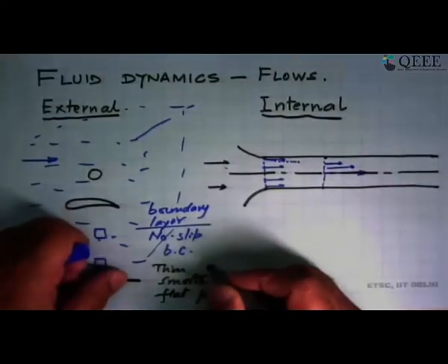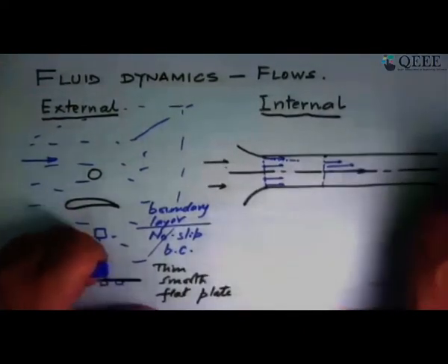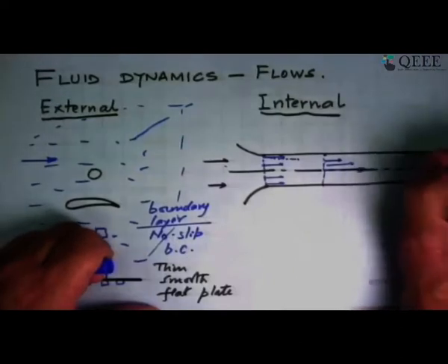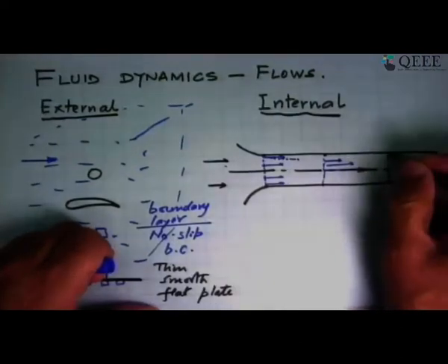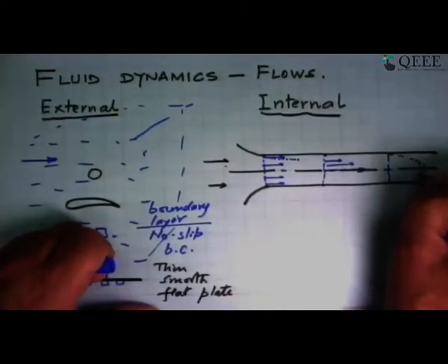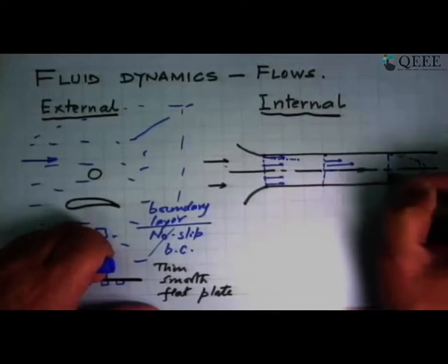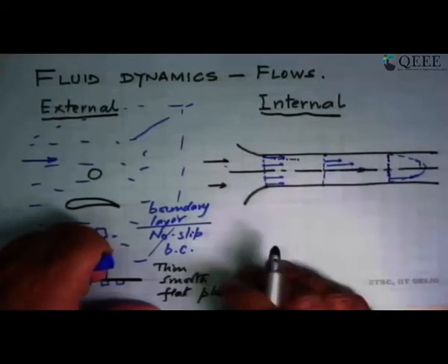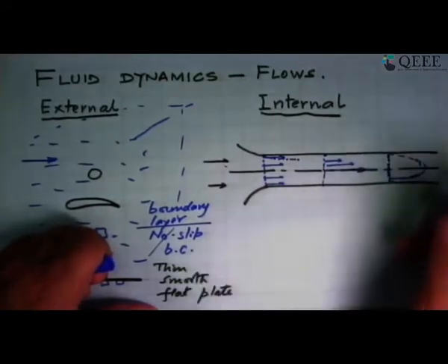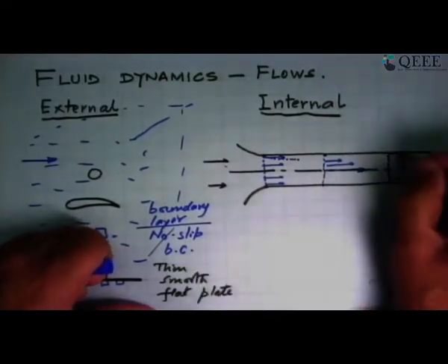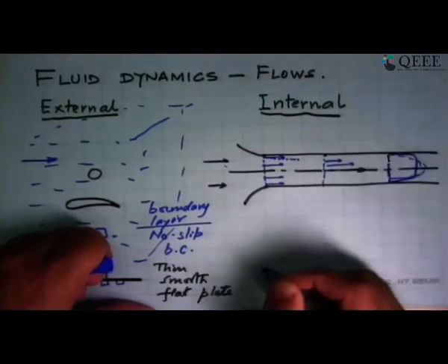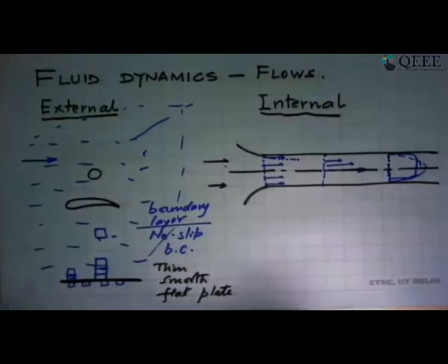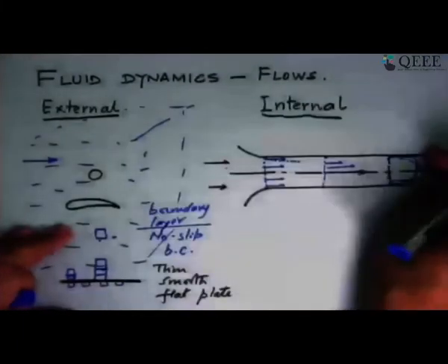And in fluid mechanics we have learned that if you allow this to go on for a long time, after some point you will get a particular profile there, which for a laminar flow, that means the velocity at all these points, has a parabolic shape. For turbulent flow, it has a slightly different shape, which is a flatter shape. So that's what the hydrodynamics tells us.